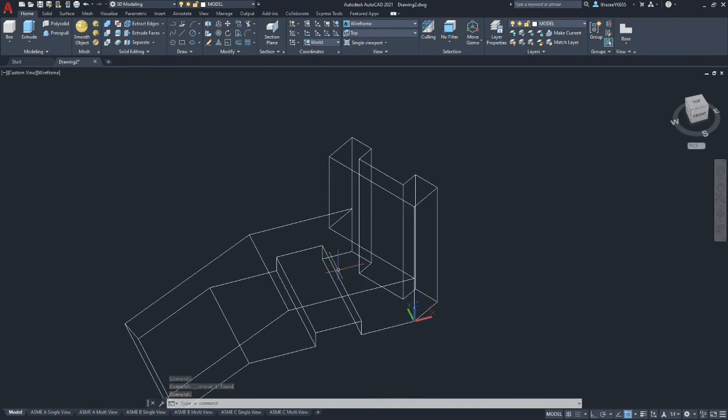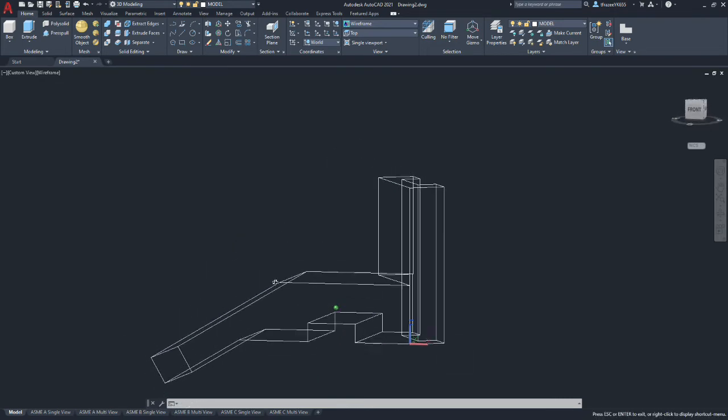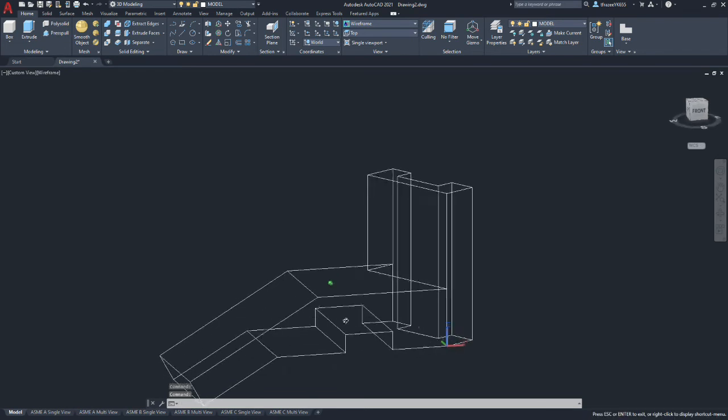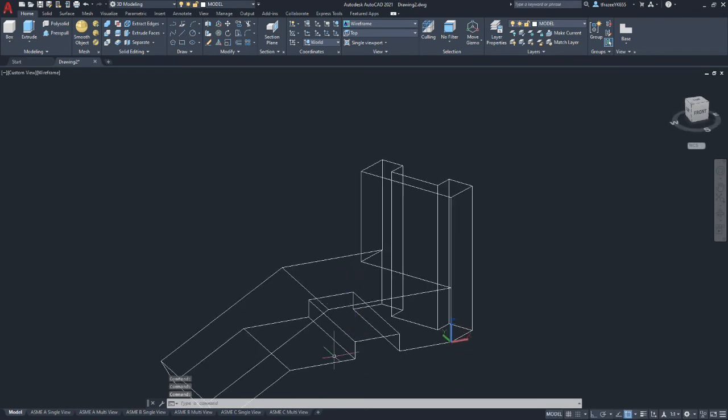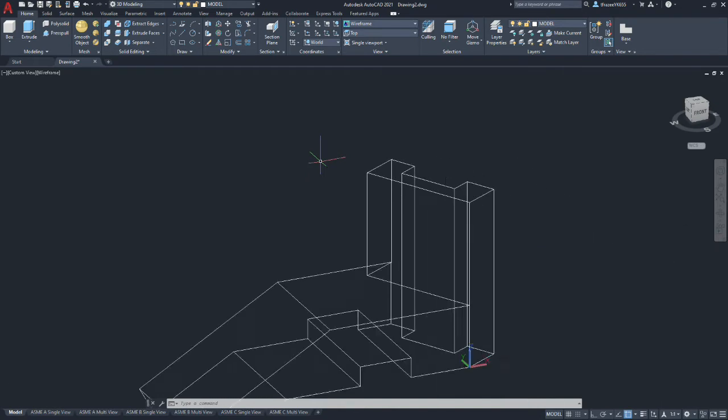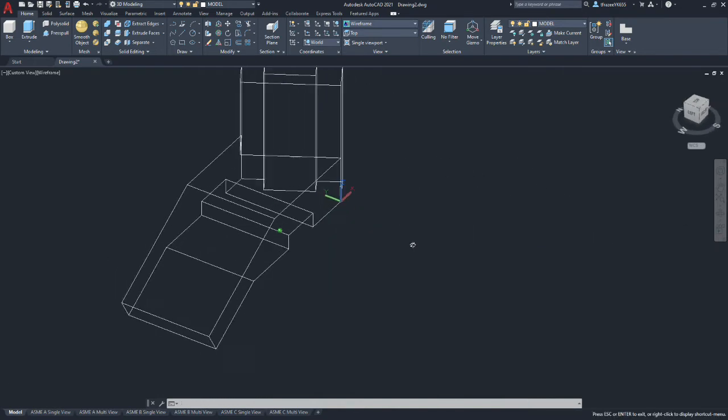Okay, so now we're going to put a hole in the top face here. Now I noticed, I modeled this once before, the hole, it's not clear in the drawing, but this hole actually intersects with one of the inside faces of this slot. So I'm going to opt to put the hole all the way through the part as opposed to having it terminate at the slot. Okay, so to do so, we need to again create some construction geometry.